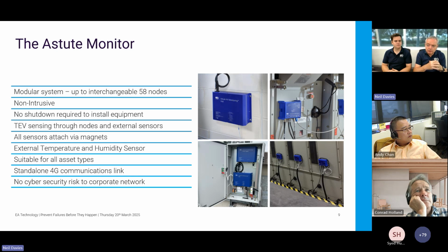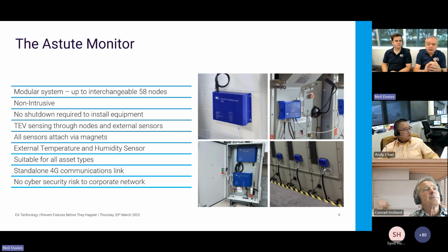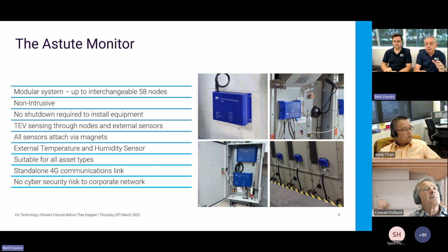The key thing for retrofit onto older equipment, which is a lot of what we're going to be talking about today, is that you don't need a shutdown to install it. So it's completely non-intrusive. You're not having to take an outage. You're not having to go and install sensors anywhere in the system. Okay, so the TEV sensing through the nodes, and there are also external sensors that can plug into the nodes, so you can have 2 per. They're all basically magnetically attached. Communication, we usually do via a 4G modem, so it saves you going into your corporate network and all the cybersecurity risks and 1,000,001 questions from the IT department.